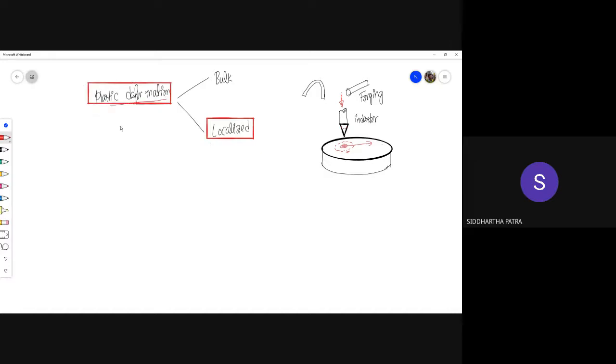And in the viva, if I ask you what is the definition of hardness in relation to our experiment, the statement is that it is the resistance to localized plastic deformation. The example being an indentation or maybe a scratch. So instead of taking this sharp nail-like object, I can take a knife. I can imagine a sharp knife edge, this one, and try to make a scratch.